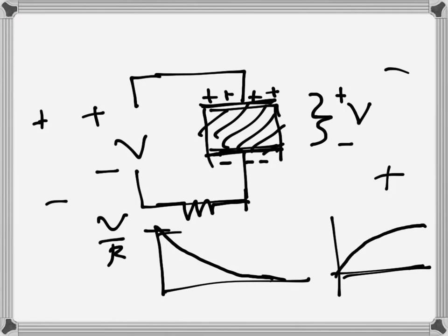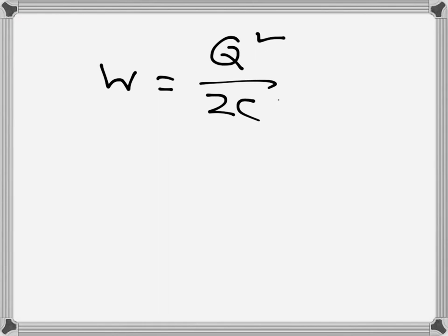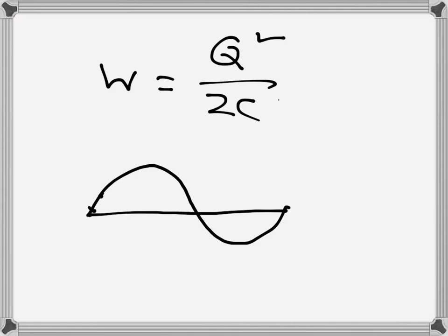The voltage across the capacitor for a DC applied voltage will be like that. So this final voltage will be V, the applied voltage basically, and the initial voltage will be 0, because initially it's a short circuit, and after the end of the transient it's an open circuit. So when an AC voltage is applied, for any instant we can think of it as a DC in that instant. So every instant will give rise to a transient current.